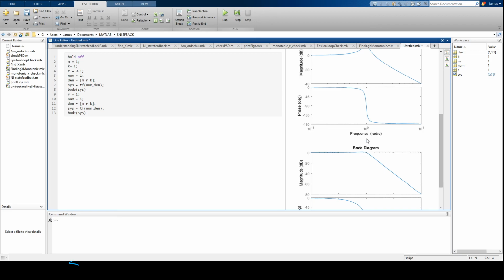By changing that dampening, not only have you lowered the peak, but you've also changed both sides of the response, and you just need to consider exactly what it is you're looking for in your overall control objective to say whether or not that's okay.